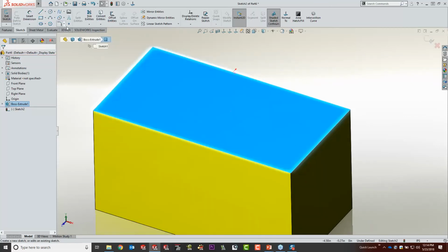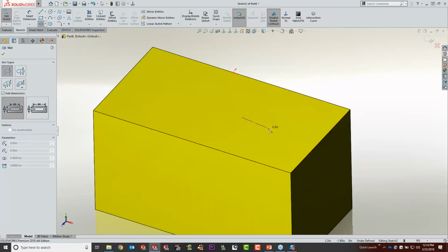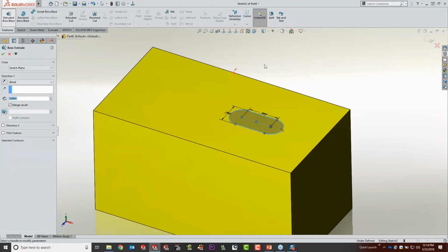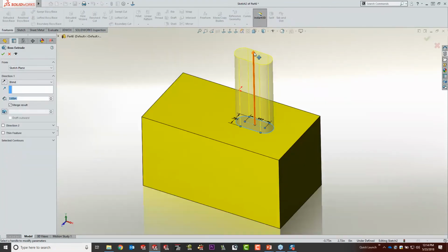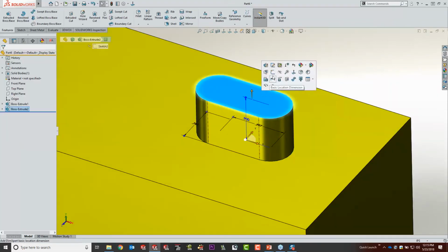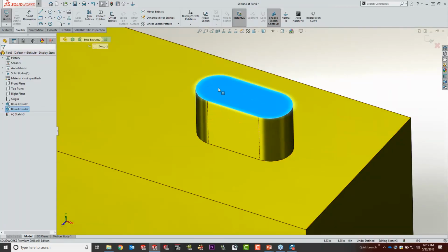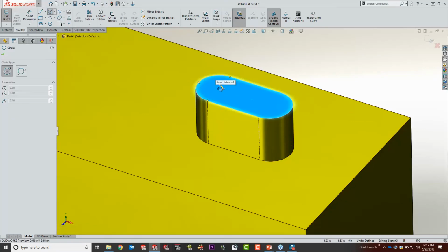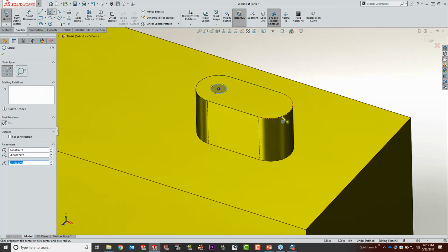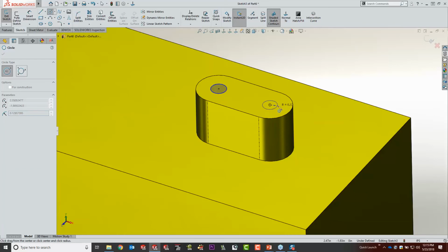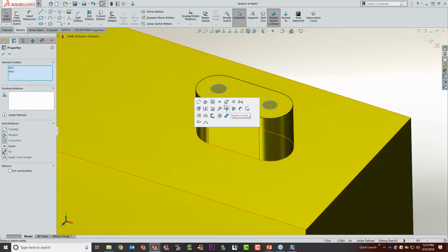When I start a brand new sketch there, I'm just going to create something that theoretically here we would reuse. So I want to create a little bit of a slotted shape. And the slotted shape will have an extrude distance to it, and that'll just be an original distance. And then what I want to do on top of here is just drop a couple of holes on here. And again, without being very specific in the interest of time, let me just throw these 2 holes right there in the center. And I'm not going to worry too much about them other than just quickly making them equal.